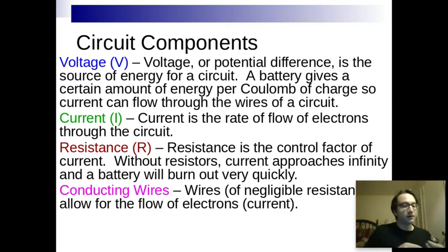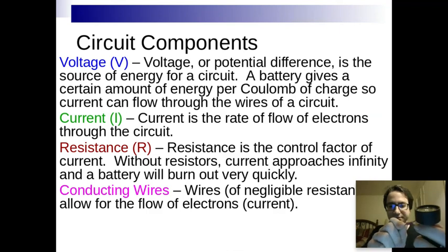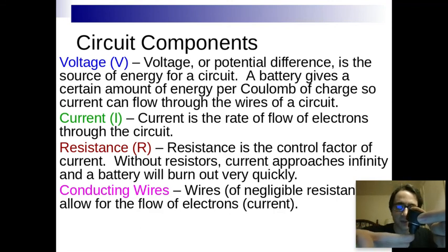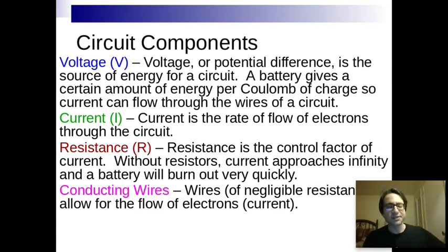So the way any light bulb works, we need to connect the side of the bulb and the bottom of the bulb, one for each connection. If you look closely at a light bulb, when the wires go through the filaments, one wire goes to the bottom, one wire goes to the side. If you have wires going straight through the bottom, it's not going to actually go through the filaments of the light bulb to make it glow. You're just going to pass right through it, like it's not even there. You'll see a little bit more about that when you eventually get to your simulation assignment later.